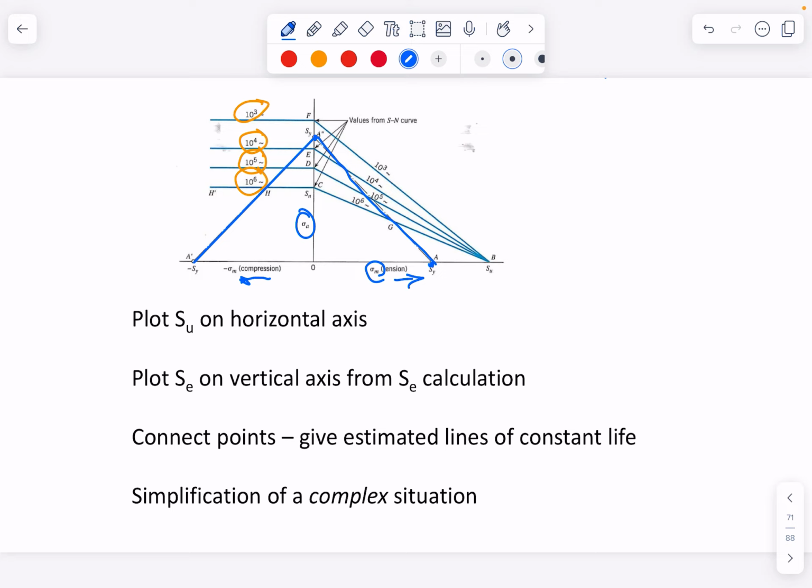But if you're designing for Formula One motorsport, for example, you might have data that shows a particular component only does 1,000 cycles in its life. And so you're better off optimizing it to do 1,001 cycles and save a few grams. Same in aerospace. If you really understand what your product is doing, then you can much more tightly optimize it.